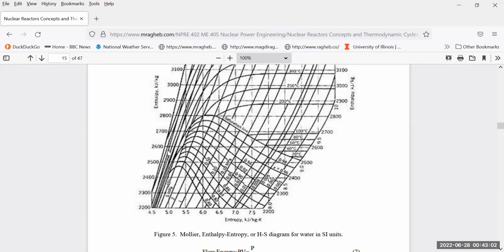You'll find that it goes up here, reaches a maximum point, and then comes down. And this is subdivided into ranges, 0.8, 0.98. This is the quality of the steam in that case. This is called the saturation line, where at that point, say, it's 0.94 steam and 0.06 liquid. When you add the heat from the left side to the right side here, you turn your water into steam. And when it is 100% steam, the quality factor is 1, and that's what we call the saturation line.